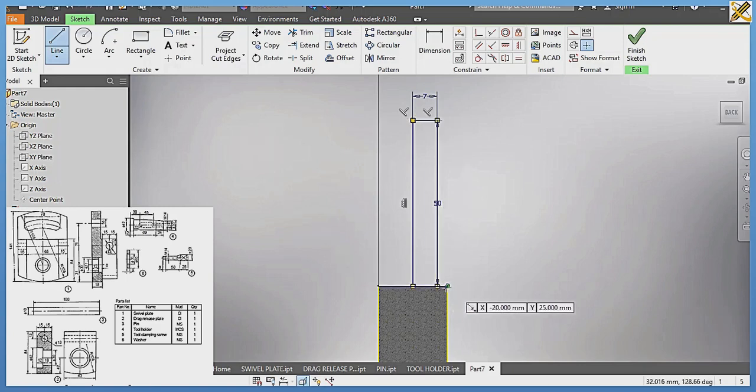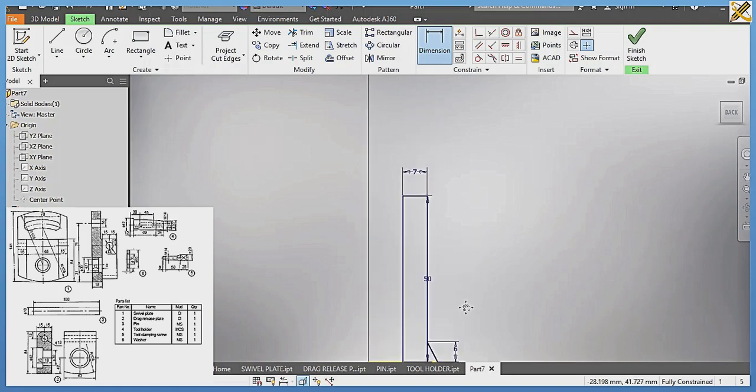Picking from here to that area, then dimension, down here is going to be 6. Why do I use 6? By the time I chamfer, if I chamfer a circle of diameter 6, or if I fillet a circle of diameter 6, I'm going to use a chamfer of either 3 or fillet of 3, and it's going to give me a conical head. So it's that same principle I'm applying right here. Okay, so that is that about that.